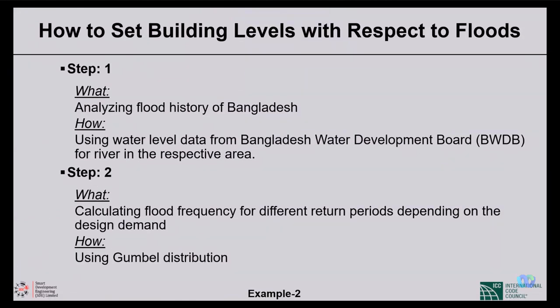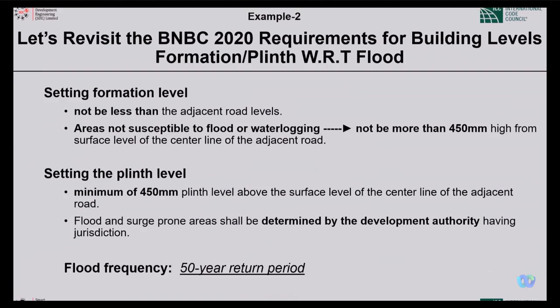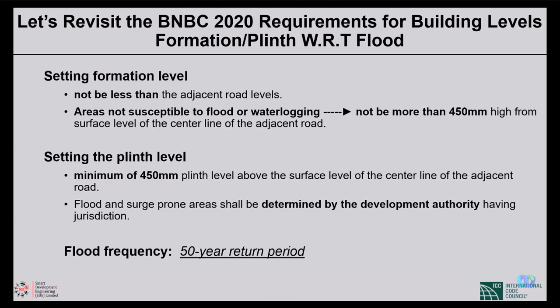So now the second example, what we are talking about, the flood frequency analysis. In the flood frequency analysis, you have to understand two things. One, which data I'm going to use, which are my controlling stations for my site. That is very important. And the second one, a method to analyze those data. So which data is important for me, and which method I can apply to get my flood frequency analysis. So these are the two things.